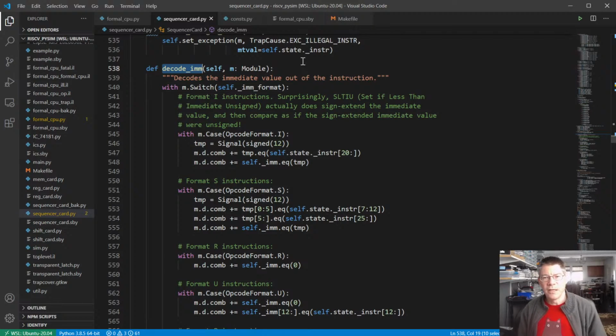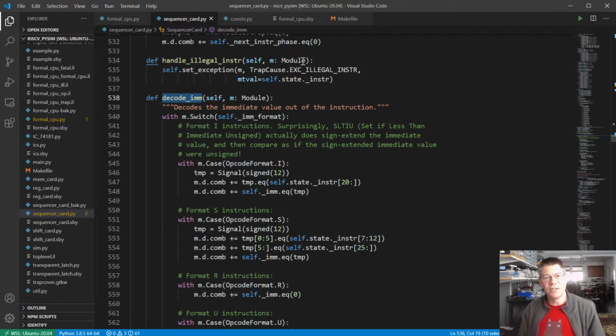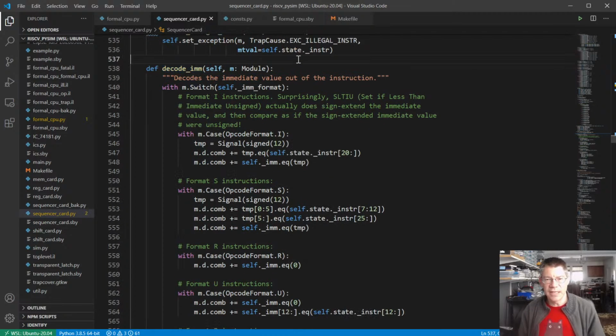So we know that we're going to need some 74 16244s and a GAL. And of course, the GAL is just going to be some logic. It's not going to be a standard chip because it does have to be programmed. I could replace it with a bunch of gates, but then it would be messy and stupid, and I hate it, and my life would suck.